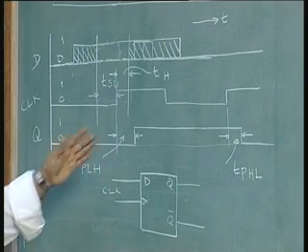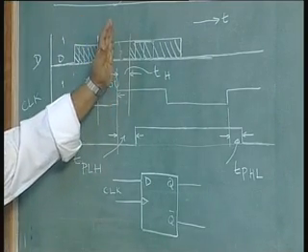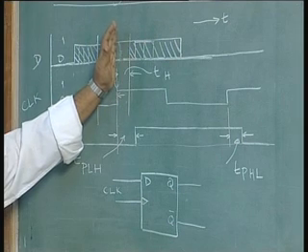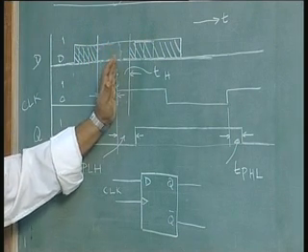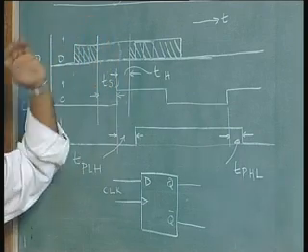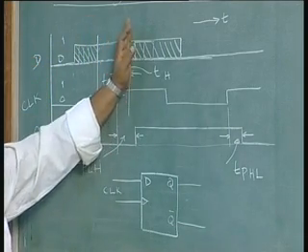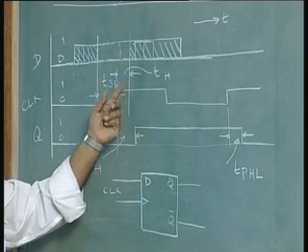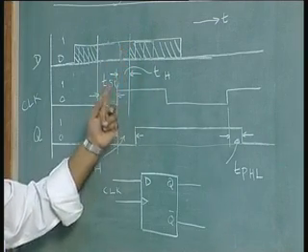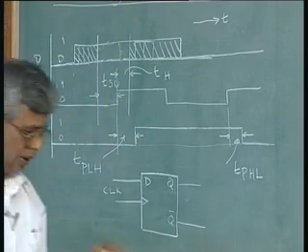And then we are talking about 2 other terms. One is called the setup time: the interval before the clock transition at which the input should be stable. And the hold time is the period for which the input should be stable after the clock transition has occurred. So, let us write this here.